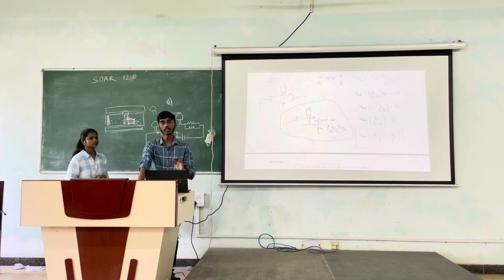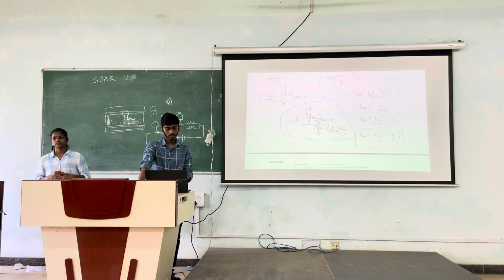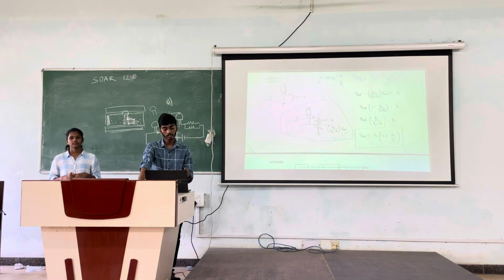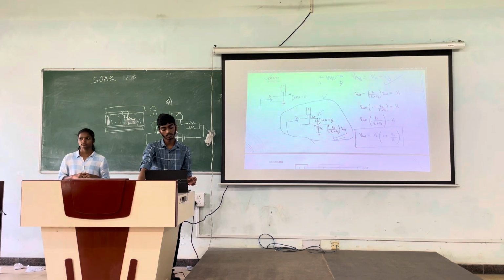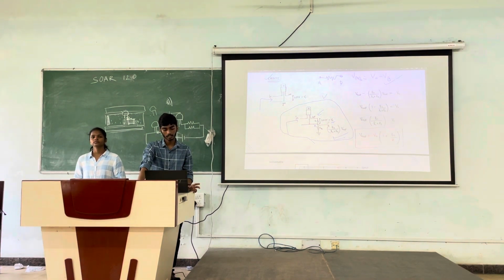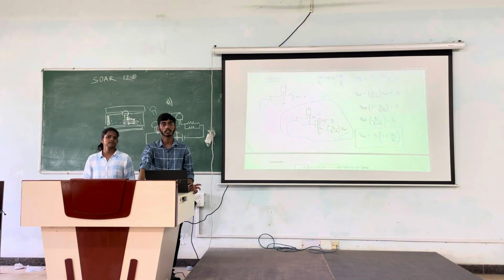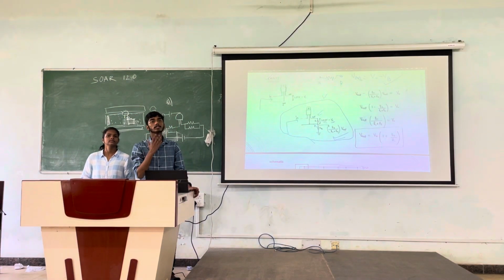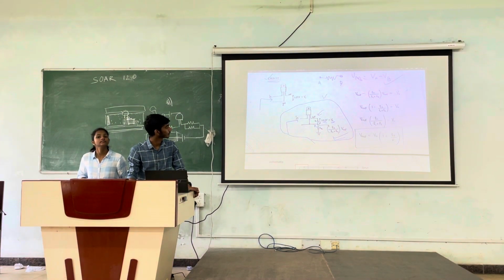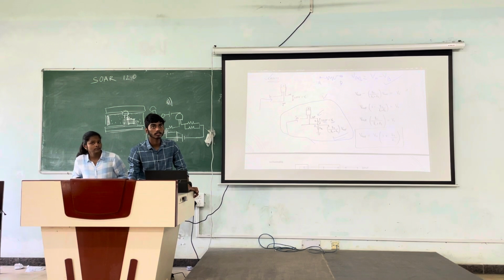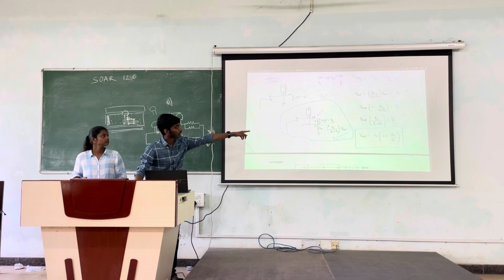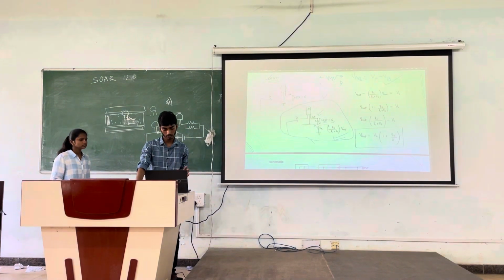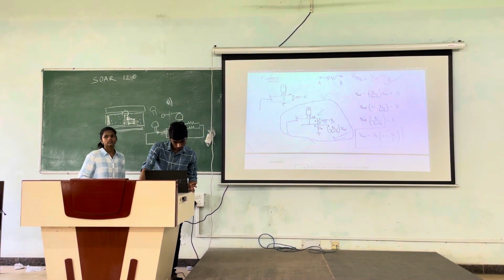Are you guys getting it? These 2 points, if we take the difference, we get a potential difference which is equal to V naught. In this case you can say 1.25 volts, but we are generalizing it as V naught. Use this rule R2 upon R1 plus R2 when both the resistors are in parallel? No, actually this one is the voltage division rule. Let me tell you first.